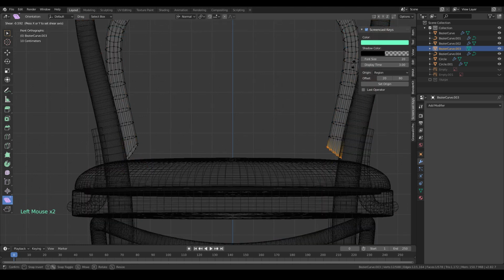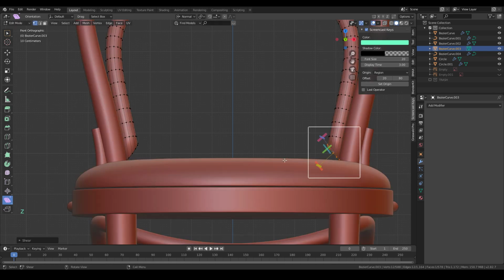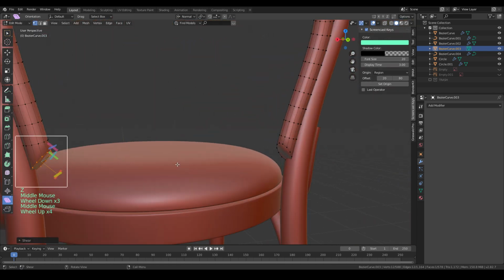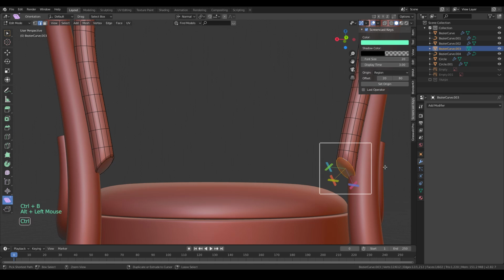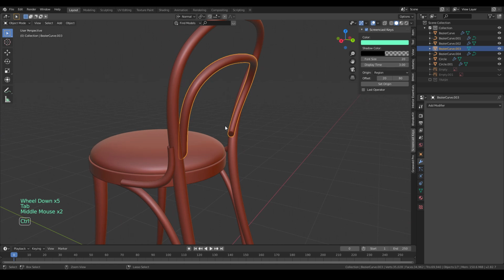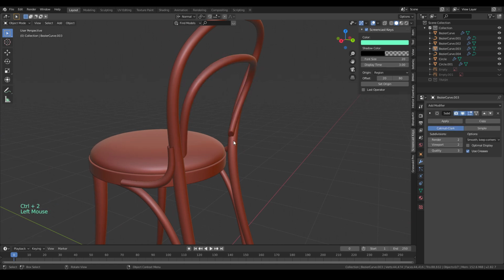And then this one, okay, that's good. Bevel it. This one too. Oh, this one, just hit Shift R. If you already done this one, like so, you can choose Shift R to repeat the last operation. Okay, and then Control 2 to add a subdivision.